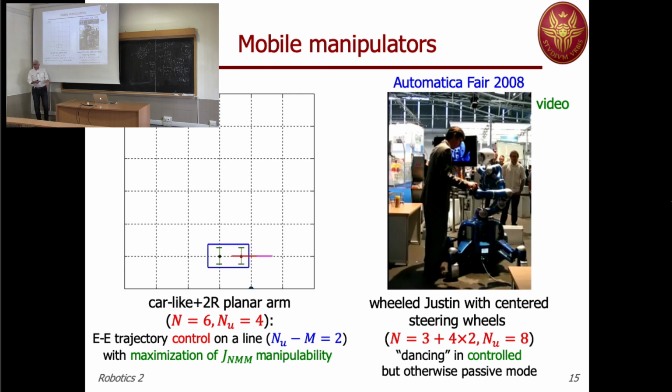So whatever we have done so far will include also kinematic control, since we are working at the first order level. So in terms of velocity, we will need a term proportional to the error added to the desired task velocity. But this, no matter what, we have to follow this trajectory in position.